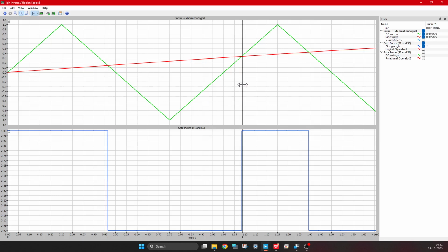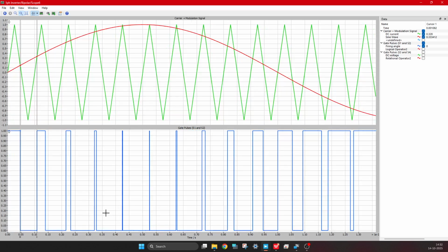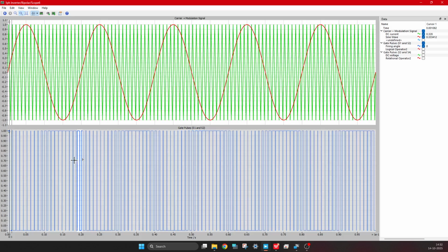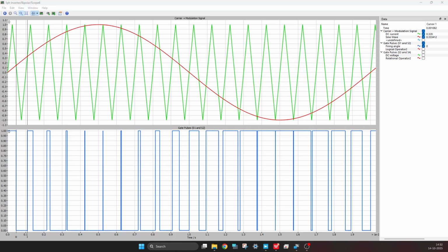Okay. Now in this duration, you can see that it has a low state. Why is this a low state? Because the triangle is lower than the modulation. Okay, and a similar pattern follows in the whole duration. You can see that here it is quite high and it goes to minimum, then slowly the pulse width changes and it goes to maximum. So if I look at the whole signal, the pulse width changes sinusoidally, right? It is changing sinusoidally.